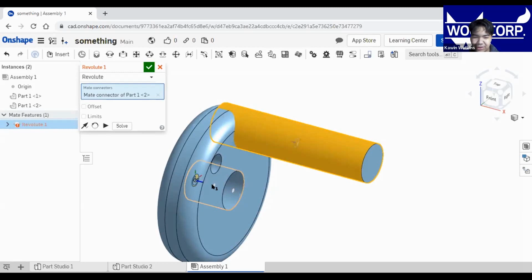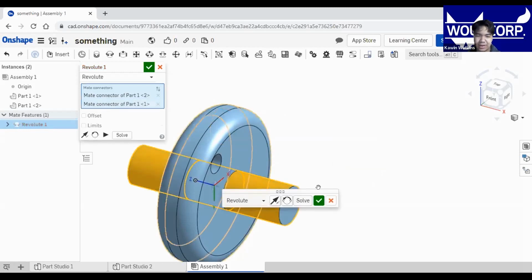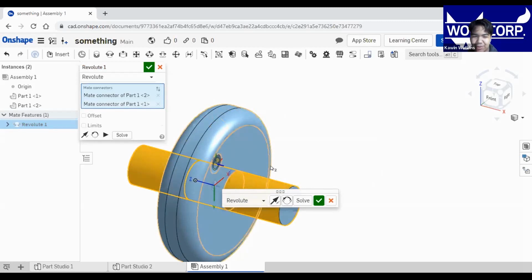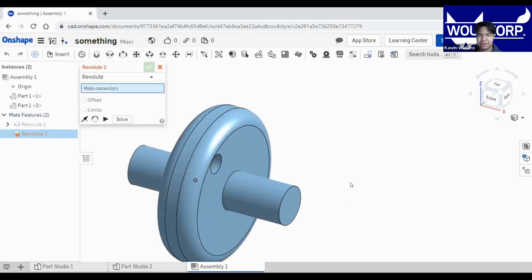And then you should see 3 mating points pop up. And then all you need to do after that is line it up so that the icon is in the middle, and then click on it. And what this does is it basically lines the wheels up with each other. So then click on the green check mark, and then on the window, click the X.